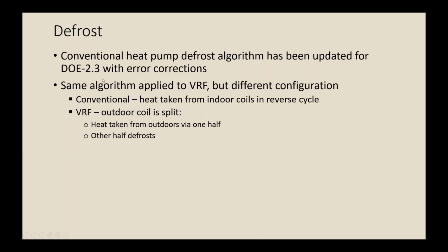Another technical topic is defrost. We were developing the VRF, and we found we wanted to be able to compare VRF systems to conventional heat pumps, and we were getting some odd results when we started looking at the defrost energy of a VRF compared to the defrost energy of a conventional heat pump.